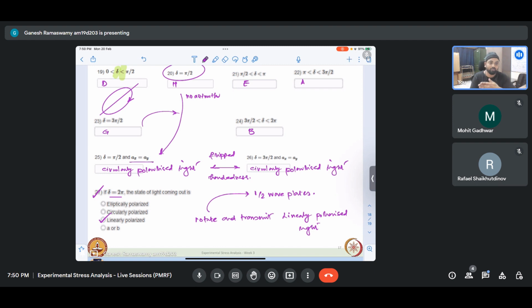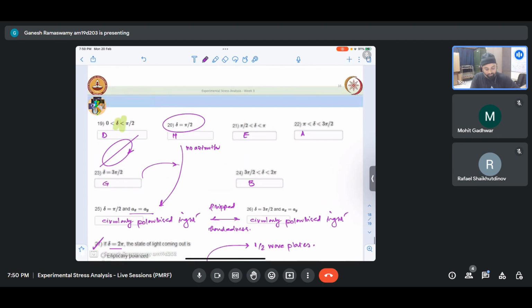So in a circular polariscope, essentially, we have a light source. Then we have different optical components. Each of those optical components can be represented by a matrix. Once we operate that matrix over the impinging light, that is the exit light of the previous element, we'll be able to gauge what will be the exit light at our end. So in order to understand all that, we need to understand how a rotator and retarder works. That was the emphasis behind this. So I hope this has been clear.